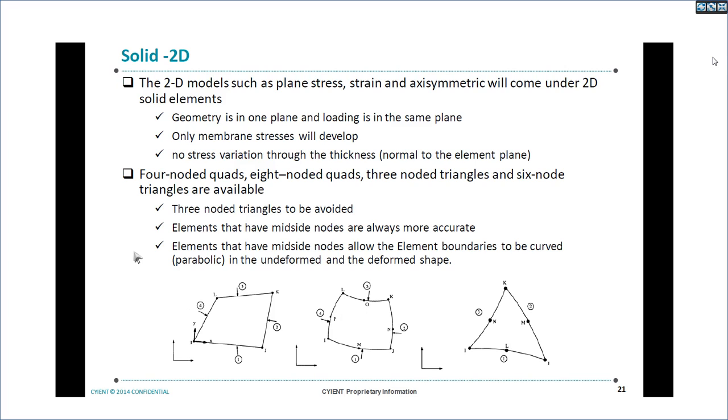This is the axis. In ANSYS, we typically call this axis Y. The geometry should be aligned such that the cross section axis is along Y, and this is the radial direction X.